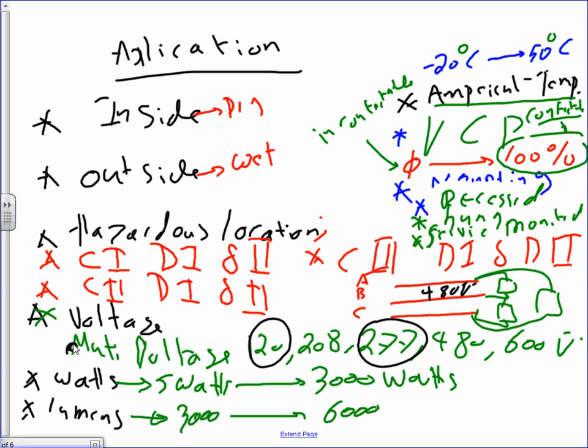Typically in a commercial building, almost always recessed. You have a false ceiling like the one above your head, and they're all recessed in the ceiling. In an area where you want the people to feel comfortable, they use direct, indirect light, and they suspend them down so they can shoot light up. Can you guys look at the ceiling? Is the ceiling lit well? Does the ceiling look dark to you? So if you suspend this fixture and have direct, indirect light, it will shoot light at the ceiling, so the ceiling will look exactly like the walls, really well lit. Who cares? Some people feel comfortable in this environment when the ceiling is really lit, the walls are lit, and the floor is lit. They feel comfortable.